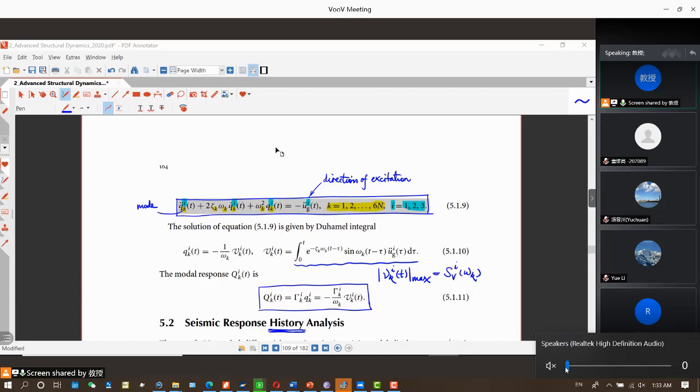And in many regions, for example, in northeastern America or in Jiangsu province, there are very few actual earthquake records available. So this method may not be feasible. The second method is synthetic earthquake time histories using stochastic methods. So this is a pure stochastic method to generate ground motions. And in this case, only a small number of parameters are used to characterize the ground motion, which can never be complete. In some codes and standards, pure synthetic earthquake time histories are not allowed. Okay, so this is not very desirable.